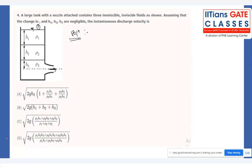Now see, whenever you are applying the Bernoulli equation between two points, those two points must be in fluids of the same density. But here, if you apply it between 1 and 2, where P atm is there, you will not be able to get the answer accurately, right? Because the density at point number 1 and the density in fluid 3 are not going to be the same. So we will consider two points which are in the same density. Point 1 dash and point 2, both are in the same liquid, density rho 3.